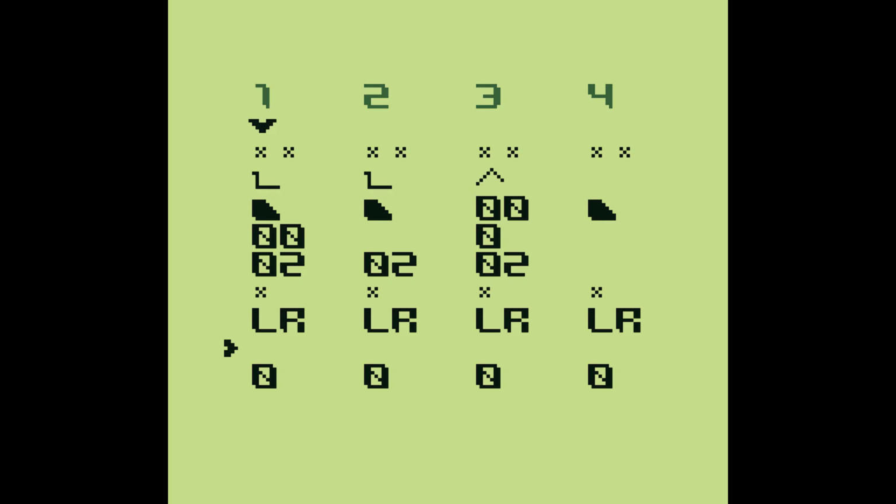Without any modification, the generator of the leftmost column, PU1, receives all MIDI signals with the address nibble of 0x0. The generator of the second column, PU2, meanwhile receives all MIDI signals with an address nibble of 0x1, the VAF generator of the third column all MIDI signals with an address nibble of 0x2, and the noise generator of the fourth column receives all MIDI signals with an address nibble of 0x3.